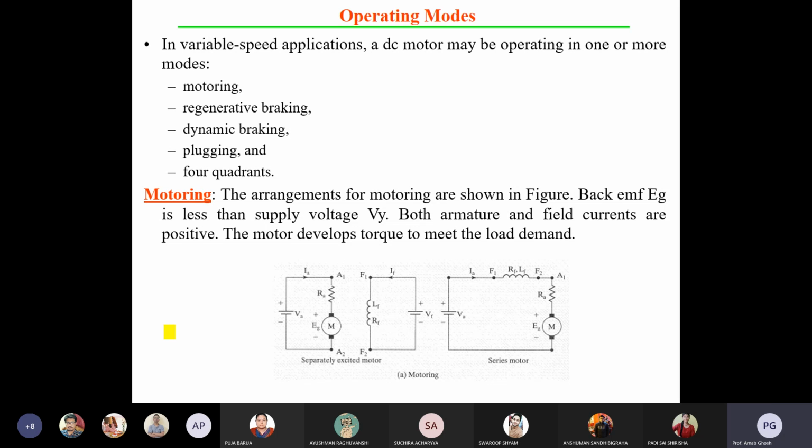The field excitation should not be altered; they are not changing the field with the changeover switch. Maybe some other mechanism, or they are changing the terminals of the motor, so the motor rotates in the reverse direction. That's why they use a changeover switch. But if it is a DC motor, a changeover switch will be there, as well as a changeover switch for your field.